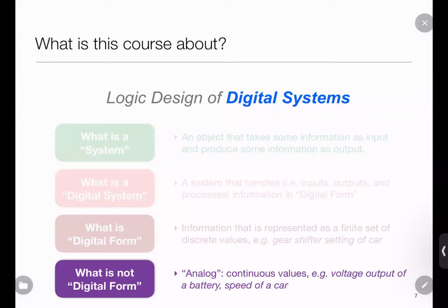I mean, if I just sample it, let's say the highest frequency is 100 hertz. So 2 times that is 200 hertz. That translates into a sampling period of 1/200 of a second. I sample the signal at that rate, and the theory says that if I know nothing else other than the highest frequency, I can recreate the signal entirely, okay?